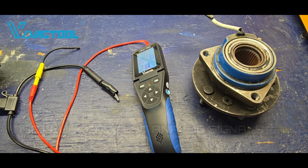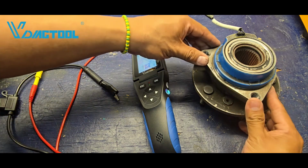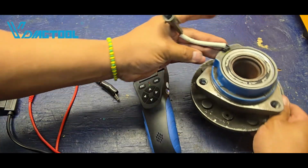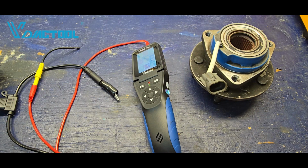Types of signals. Some sensors will send a digital signal, which is a square waveform, while other sensors can send an analog signal, which is also known as a sine waveform. In this case, we have a wheel bearing from a vehicle that has a speed sensor. Your speed sensor in this case is a 2-wire sensor. This is a permanent magnet sensor that generates its own voltage based on rotation of the reluctor wheel inside. It will change polarity from positive to negative and generates an AC voltage, and it also generates a frequency.